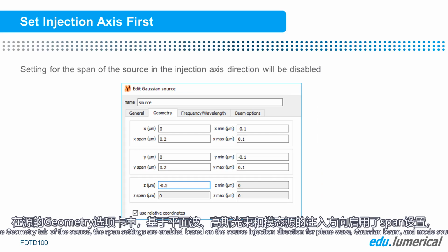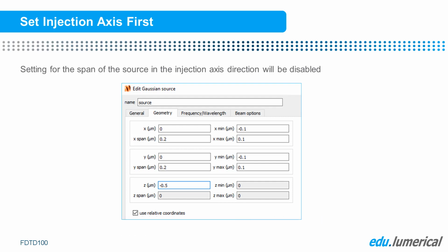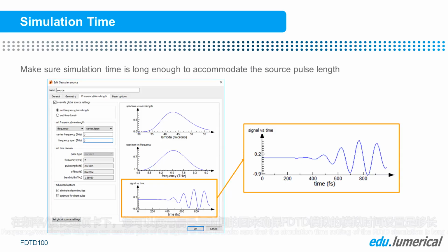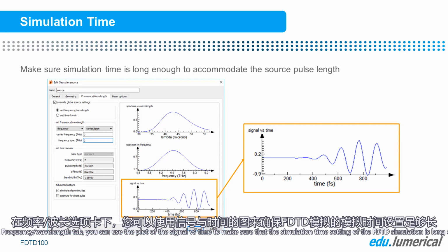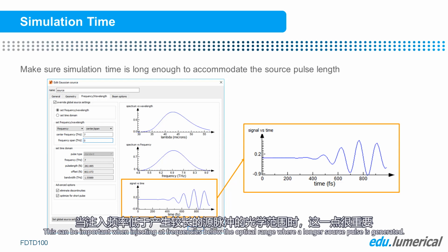In the Geometry tab of the source, the span settings are enabled based on the source injection direction for the plane wave, Gaussian beam, and mode sources, so be sure to set up the direction first before setting up the geometry. For example, if you have a plane wave source propagating in the x direction, the x span of the source is not relevant, and the setting will be grayed out in the edit window. Under the Frequency Wavelength tab, you can use the plot of the signal versus time to make sure that the simulation time setting of the FDTD simulation is long enough to include the entire time signal of the source pulse. This can be important when injecting at frequencies below the optical range where a longer source pulse is generated.